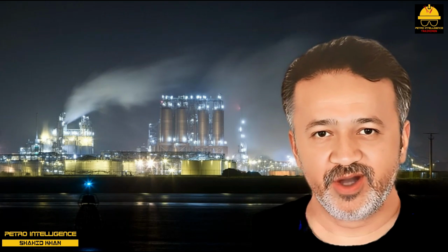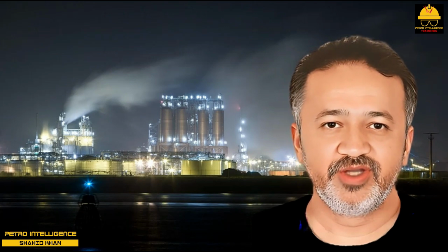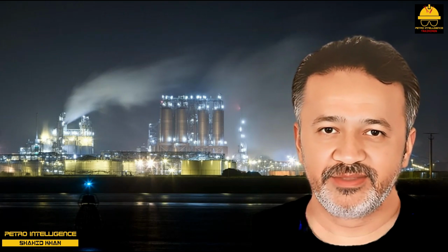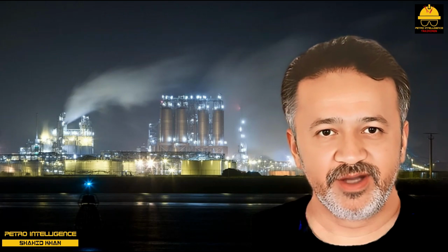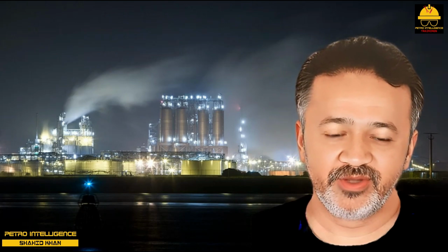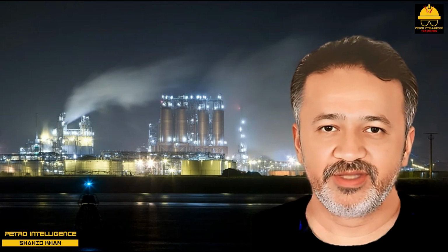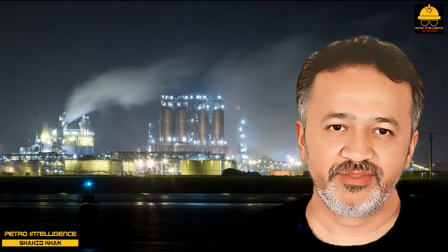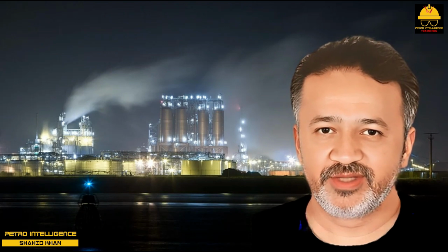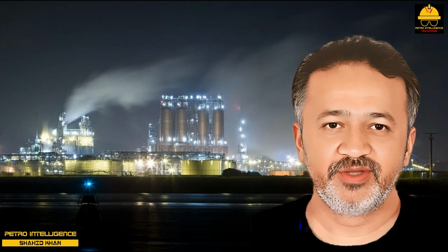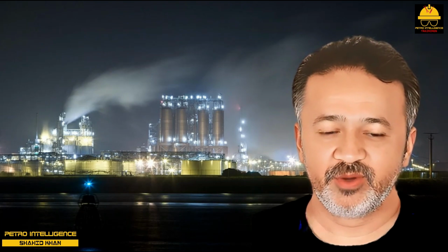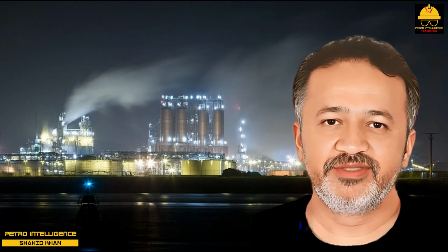Adjusting for cross-flow velocity. The designer ought to specify the baffle spacing to achieve the desired cross-flow velocity. In a 20 feet long bundle, a minimum of about 5 baffles are needed to actually support the tubes. The remaining baffles are to induce an adequate cross-flow velocity. Engineers have designed tube bundles for 30 baffles, that is, 8 inches spacing, with no problems. Just remember that doubling the number of baffles increases delta P by a factor of 8.